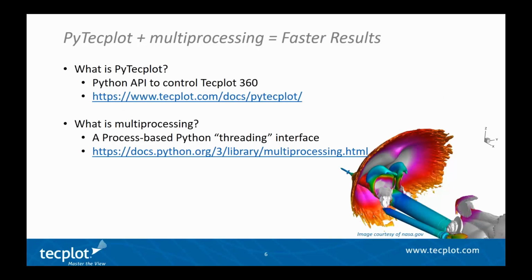So a little bit of background. What is PyTecplot? PyTecplot is an API to control Tecplot 360. You can see a link there which shows the documentation. This is a separate installation from Tecplot 360. So when you have Tecplot 360 installed, you don't automatically have PyTecplot. Because this is a Python module, you have to install it as part of your Python installation. We do require Python 2.7 or Python 3.4 and newer, and it has to be a 64-bit installation of Python. So all of that information is in the documentation. We have a very nice installation guide that can help guide you through that.